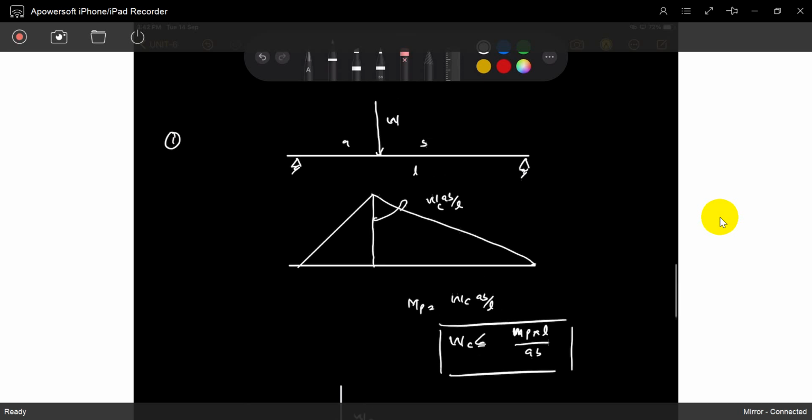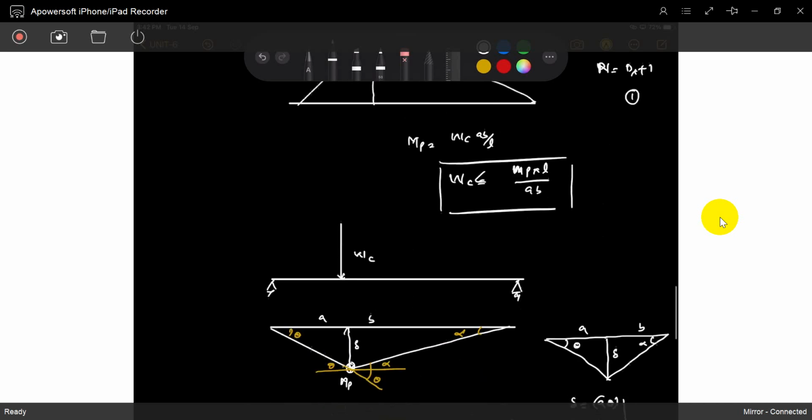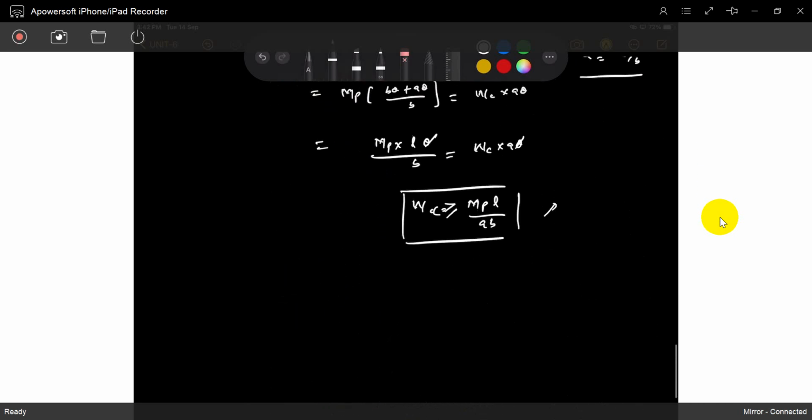So that's it. Now these are all determinate structures. DS is 0. The required plastic hinges are D plus 1. One hinge is required, acting at the maximum bending moment location or cross section. We will see later. Next level is indeterminacy 1. The required number of hinges is 2, but there is somewhat more difficulty. So that's why we'll directly do the fixed beam.